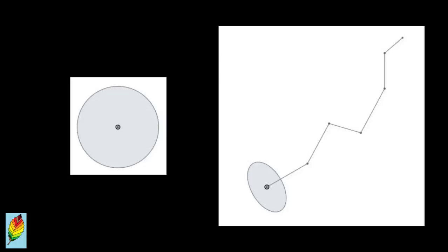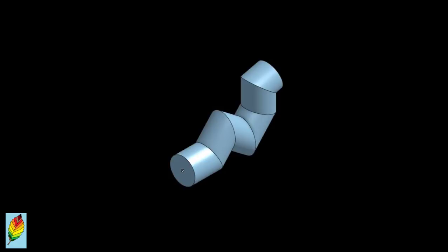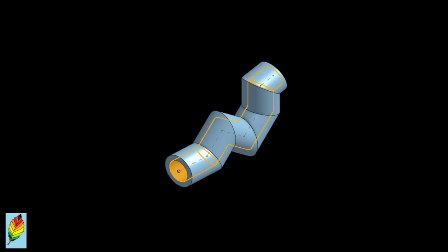An example of a sweep that adds material is when we take this circle, and this twisting path, that begins perpendicular to the circle and use them both to make this pipe. As you can see, the sweep is better than the extrusion, when the same cross-section is needed in multiple directions and the body is wholly connected together. In contrast, we can create a circle at the same end or the other end of the sweep, or at any point along the path, and then we can use the same path to remove material equally from every part of the sweep.